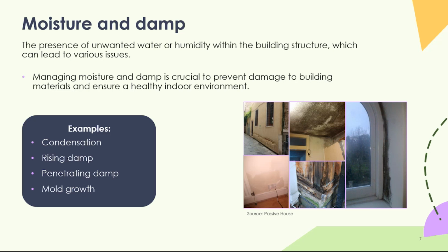There's a myriad of ways that these issues can present themselves, and sometimes you might think it's one type of damp, or we think this is rising damp, but actually it might turn out that it's just a leaky gutter and the water's running along here and along there, and it's quite confusing sometimes to find the source.